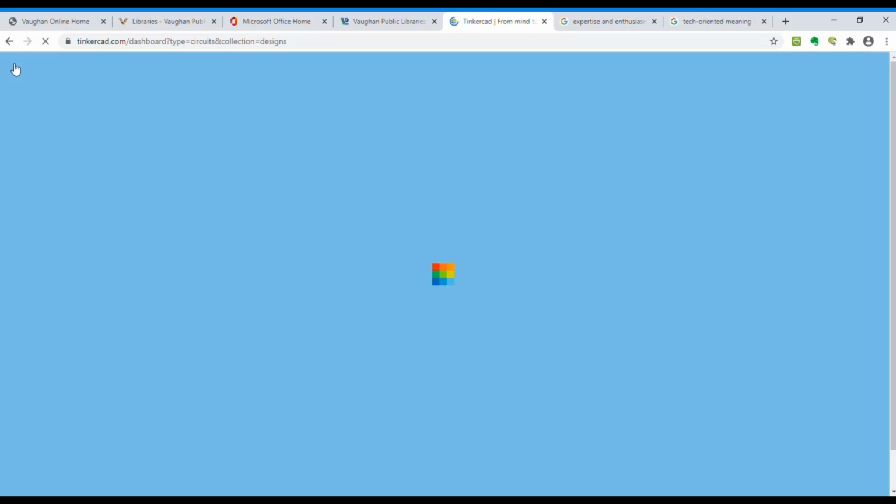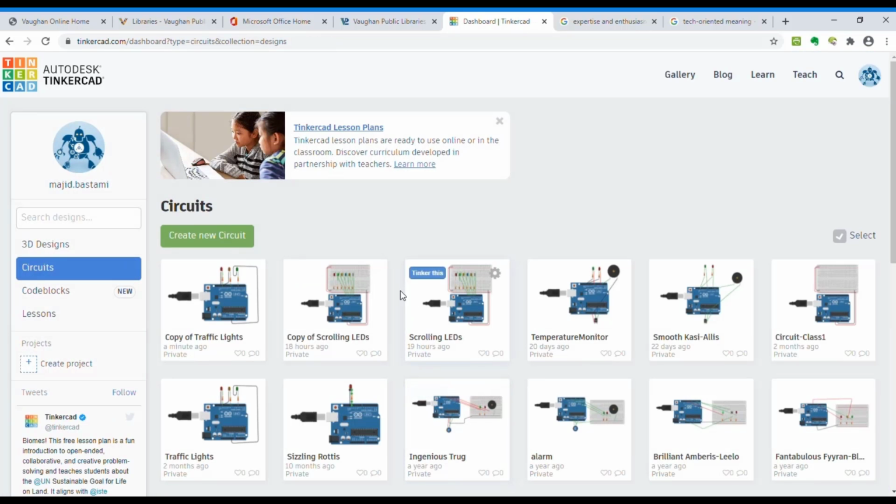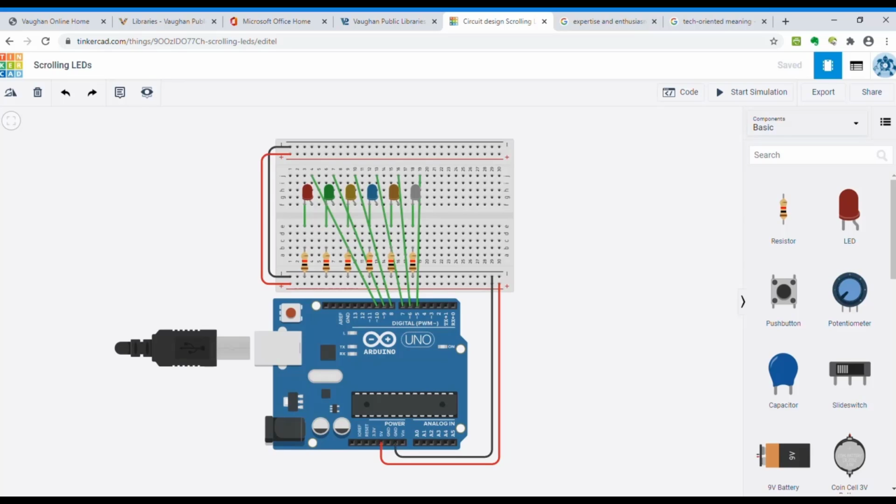By getting the idea from the traffic light, now I'm going to set up a new project: 6 LEDs in different colors, using pin number 10 to number 5. You can use different numbers. I set up based on each pin, just decreasing one number: 10, 9, 8, 7, 6, 5.